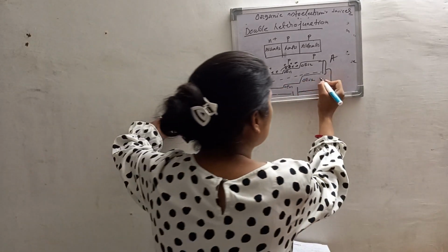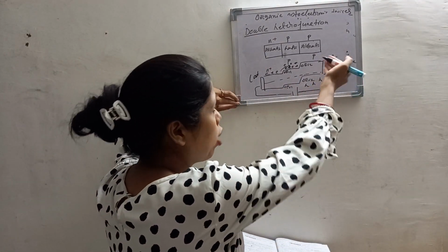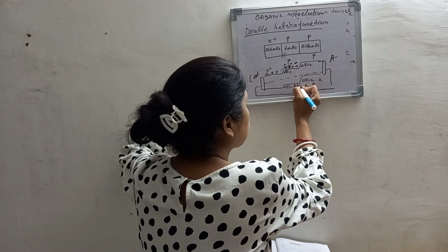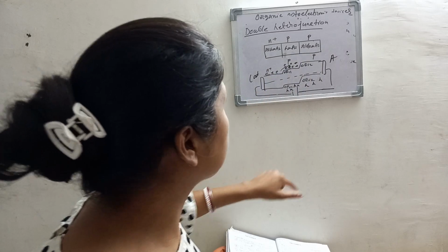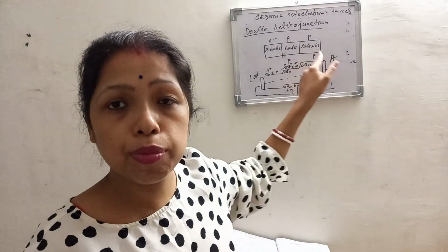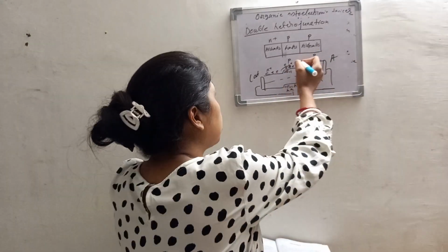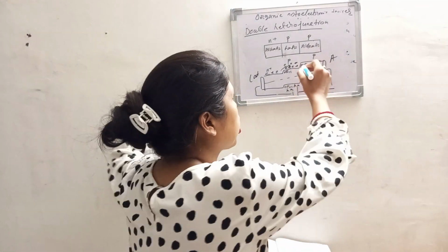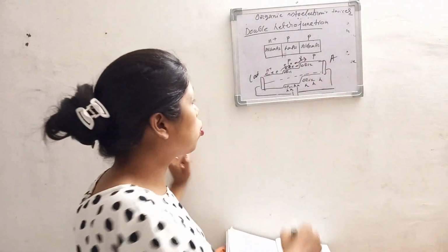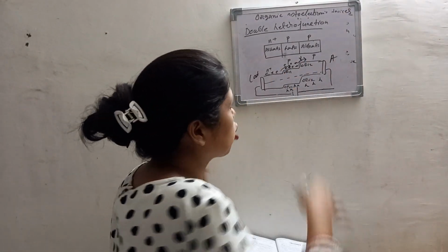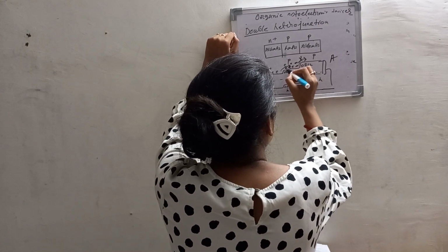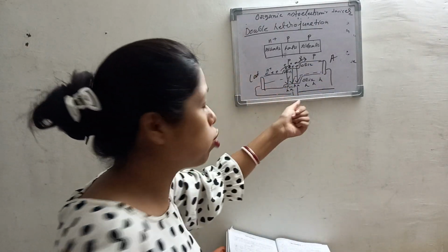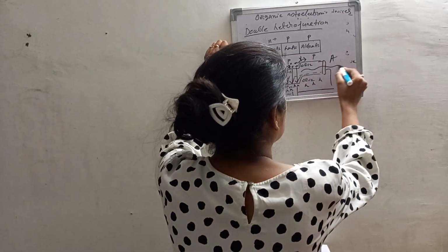Right? And in the same way, the holes are repelled away from the anode terminal and transport towards the P-type gallium arsenide. Okay. Now, as there is a large energetic gap at the interface of the P-type gallium arsenide and the aluminum gallium arsenide, the electrons cannot cross this barrier. So all the electrons present in the P-type gallium arsenide semiconductor fall down and recombine with the holes. This will produce the emission, photon emission.